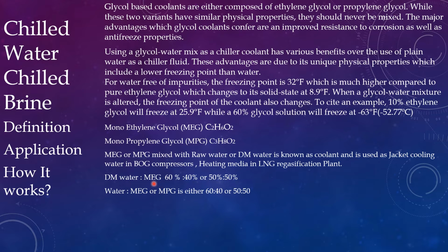DM water and MEG can be mixed in the ratio 60:40. Water 60% and 40% MEG, or 50:50. With the draw, water also can be used. Corrosion and purity is not required. You can use normal water also.